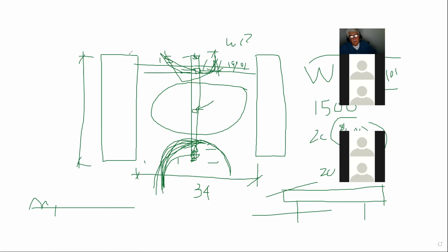And the other thing that was nice is that he's going to be building his walls right on top of this right here. He wants to make these 2x4, you understand? So he's going to be supporting the joists on 2x4 walls, and I checked to make sure the 2x4s were ample to support. And what I also told him is, if you're careful, because you know you're going to be spacing these at every 24 inches, all right? If you're careful and you know that your first joist is going, and you're going at every 24 inches,